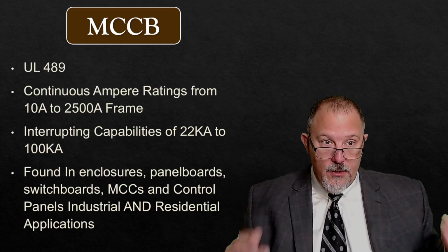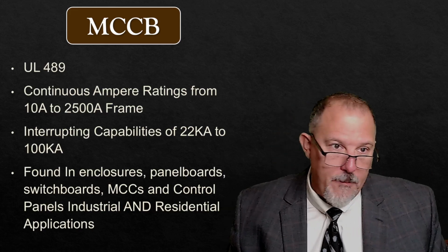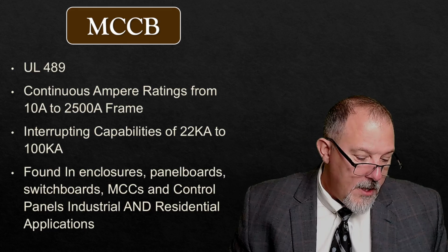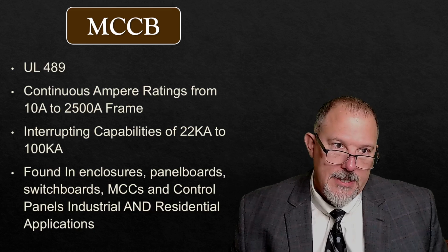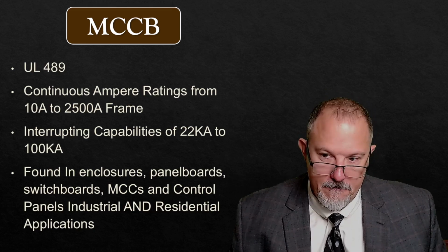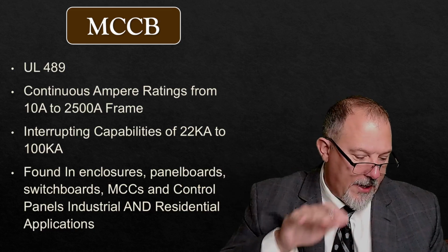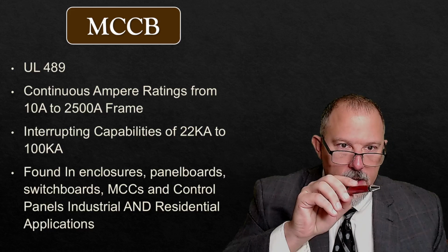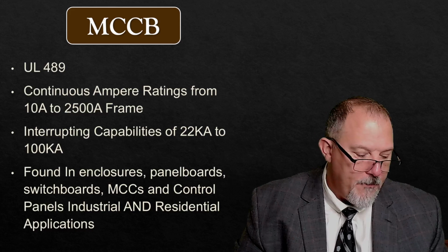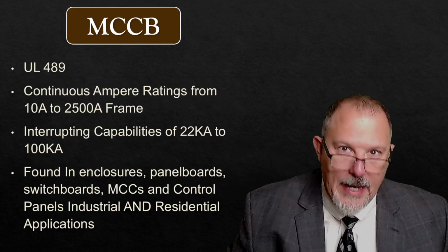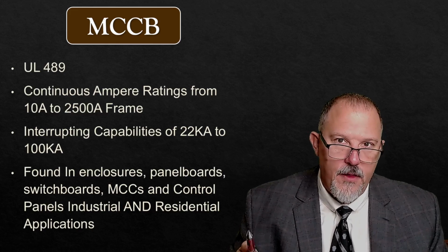Frames. Now you'll hear, remember I have a 10 amp trim to a 2500 amp frame breaker. Frames are complicated. I'm going to get into frames once I start getting into the trip curves, so I'm not going to touch on that right now. But that's the ampere range. So I have frame ratings up here that is your 15 to 2500 amp ratings. Frames are a little different than the ampere ratings.